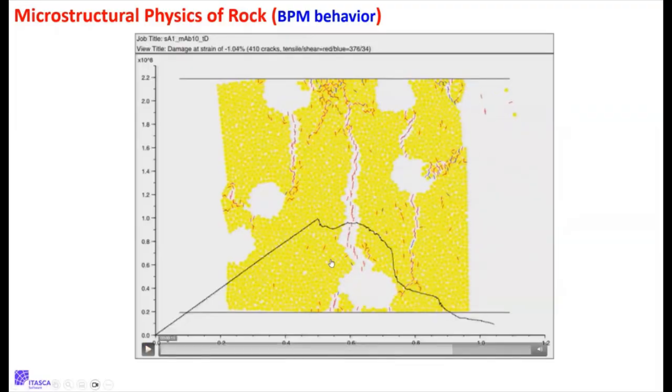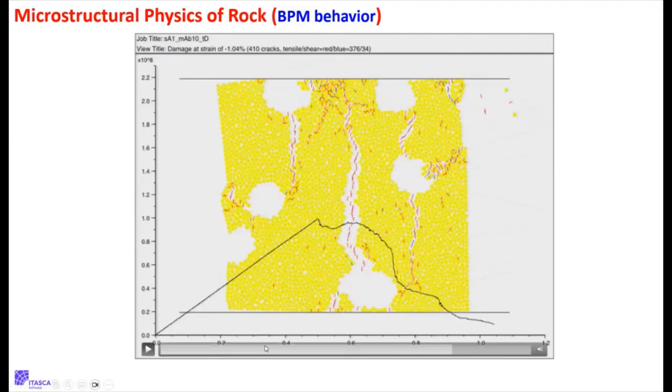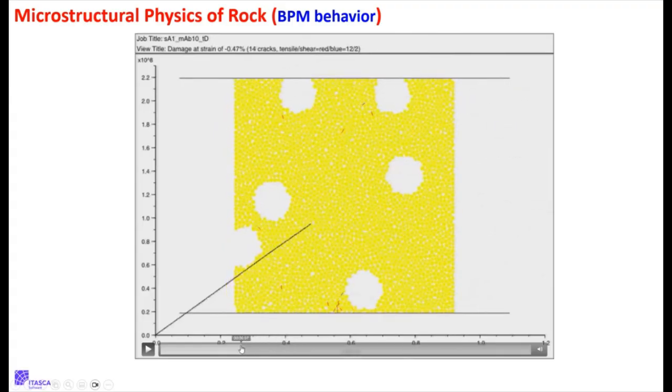Now, to be perfectly connected with this lecture, I should not have drilled holes in this. The fact that there are holes in this is making it a more complicated stress field. There is not just uniform stress, okay? And that's why it's a more complicated response than what I talked about. Notice what's happening here. Look in that upper left corner at the bottom of that top left hole. Do you see that crack forming, that fracture?